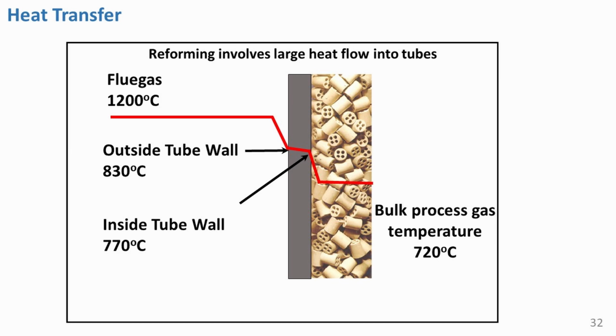Such a constraint imposes complex reaction geometry and very high temperature of the heating medium, thus resulting in very expensive construction material, a very high reaction volume, and very low thermal transients. Therefore, it causes an increase of operation and fixed cost, and a reduction of the overall process efficiency.